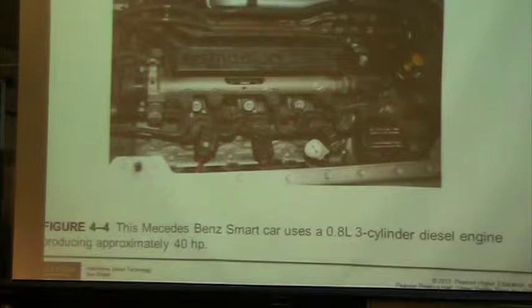You can tell by looking at this picture, I have 3 cylinders all next to each other, so it's an inline style. I can tell that by simply looking under the hood. It looks like it's going to be a common rail system because we have 1 rail that's feeding it. So there are some things we should be able to start picking up when you open that hood.